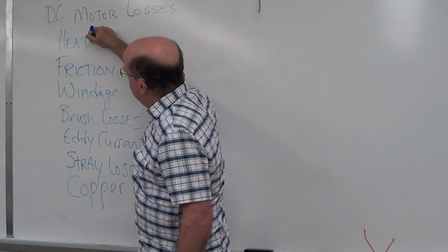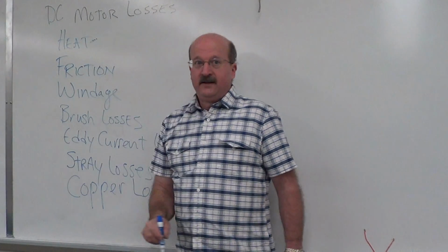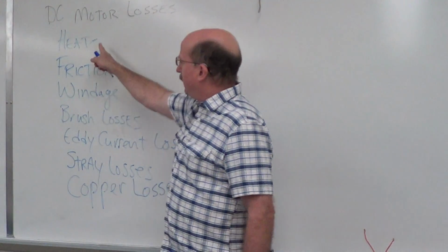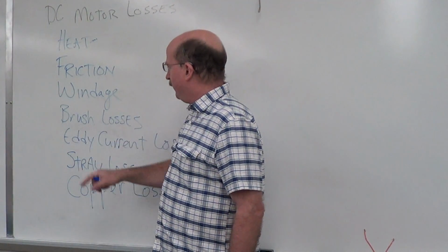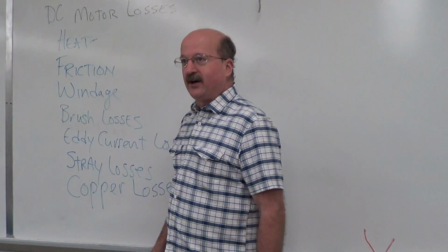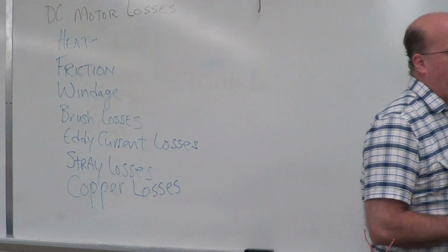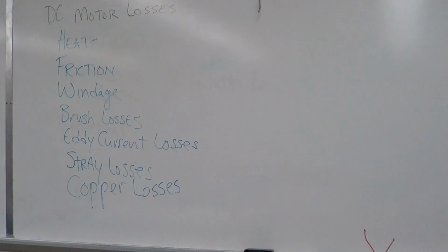Now your heat, okay, somebody threw heat out there. That comes from multiple sources. Your heat's going to come from friction, it's going to come from some brush losses, come from eddy current, it'll come from stray losses, and it'll definitely come from your copper losses.